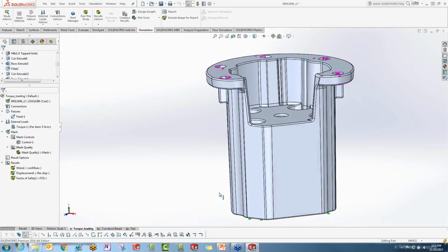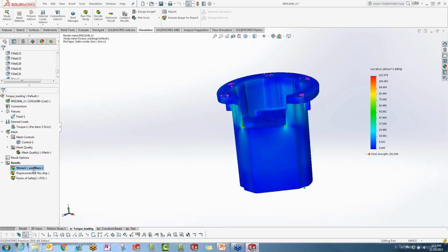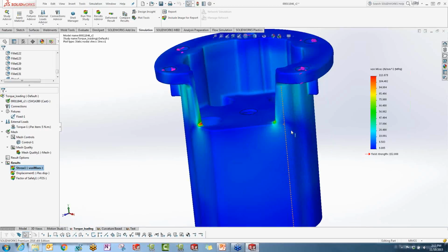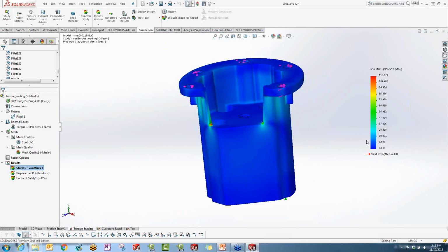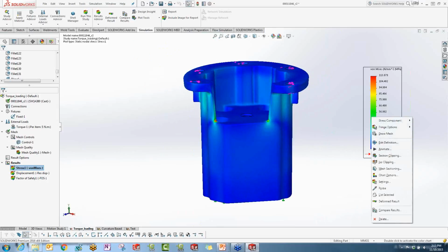Method number two is not just limited to viewing mesh when the results are not loaded. You can also do the other way around, wherein, let's say you open up your stress plot or displacement plot, and then in the past we were able to just superimpose the mesh on top of the existing result, which would be something like this.